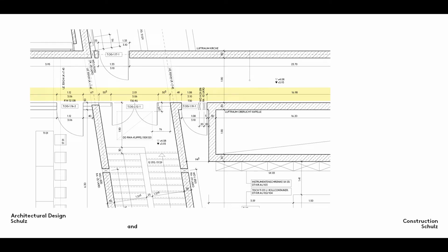Dimensions fall into different categories. Design drawings are dominated by the dimensions of negative spaces, such as the individual rooms within a building or the openings between these rooms, for example. In construction drawings, the dimensions of positive spaces, that is, individual components, are more important because these are measurements that builders need to know. The same is true of openings. The builders must know where and how big to make them. The next film provides more detail on the various types of dimension.